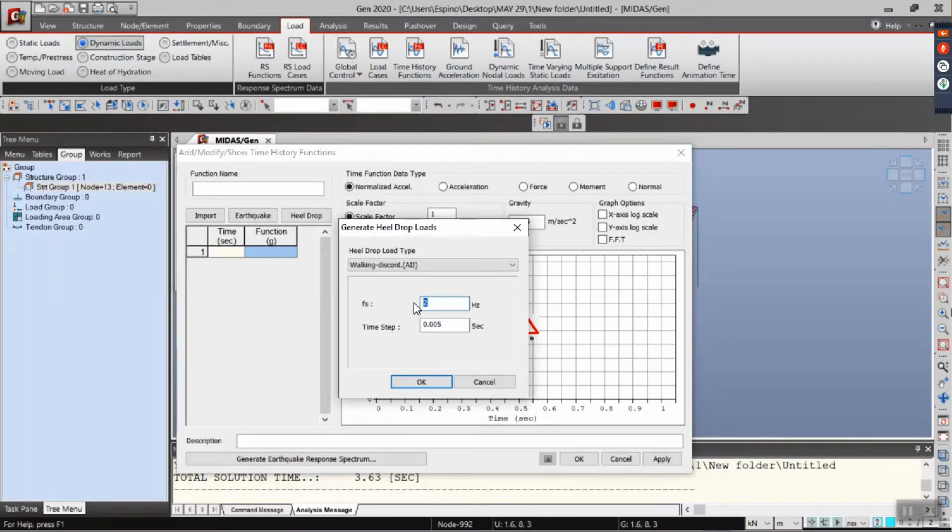So what we're doing here is that we should input the time history function in such a way that we will be simulating the most unfavorable case for vibration, that is when resonance may occur. Since we have 3.9286, if we divide it by 2, we got 1.9643. So why did I divide it by 2?